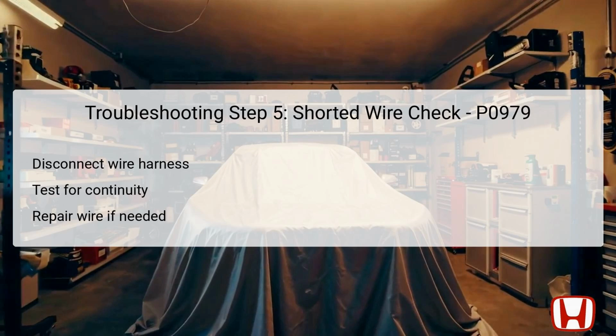The fifth troubleshooting step involves checking for any shorts in the wire associated with the SHC line. Start this process by disconnecting the shift solenoid wire harness, which typically consists of an 8-pin connector, 8P. This disconnection is necessary to prevent any interference during continuity testing. With the connector removed, you will need to check for continuity between 2 test points: PCM connector C pin 21, GRN, and a known body ground location.